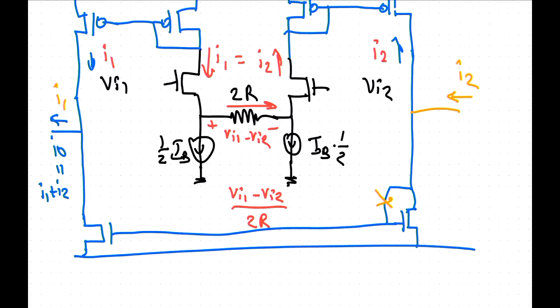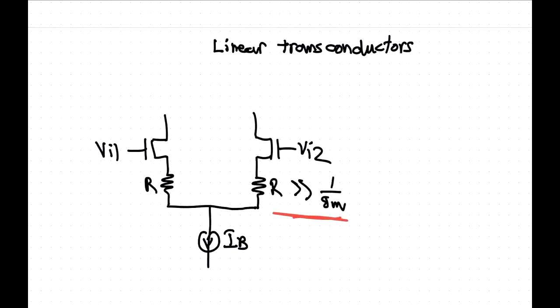Okay, so if you put in like that, now I don't really need to worry so much about that, because the effective GM when I put an amplifier from the source to the gate like that is going to be increased by the gain of that amplifier.